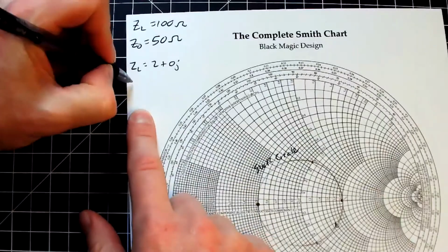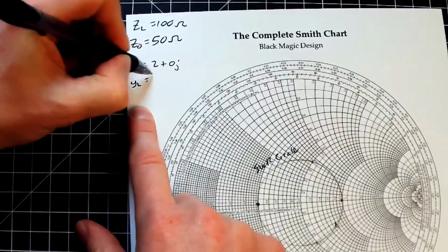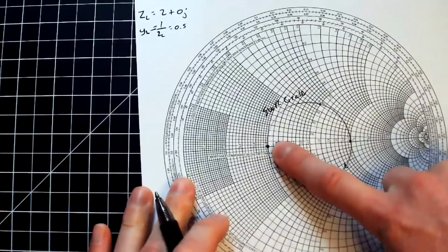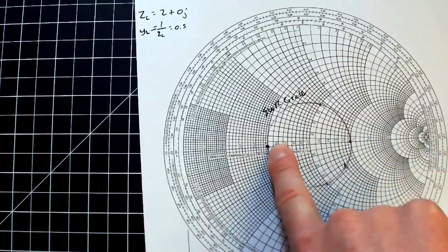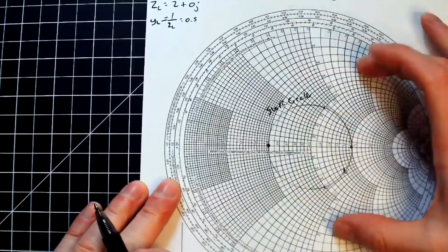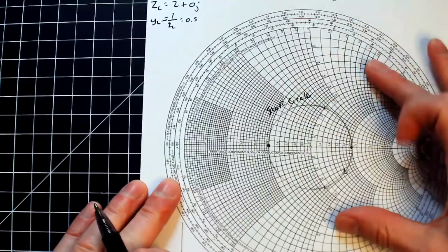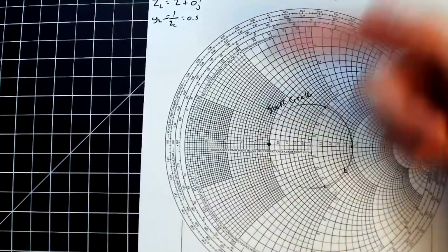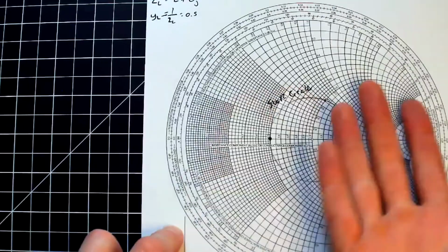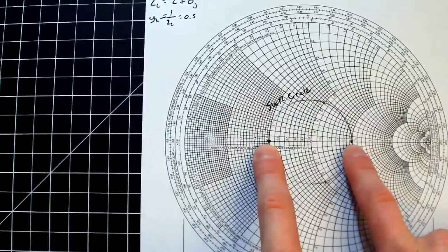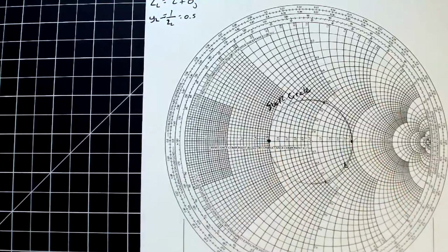Because you notice if I calculate my normalized admittance, it is 1 over little zL, which is 0.5, which incidentally corresponds to 0.5 plus 0. So that is a fun little trick, because now all of these constant resistance circles with variable reactance have now been transformed into constant conductance with variable susceptance, because everything just got mirrored and flip-flopped by the mere virtue of treating this as my starting point rather than here. That's the idea. So now step 3, well, that was step 3.